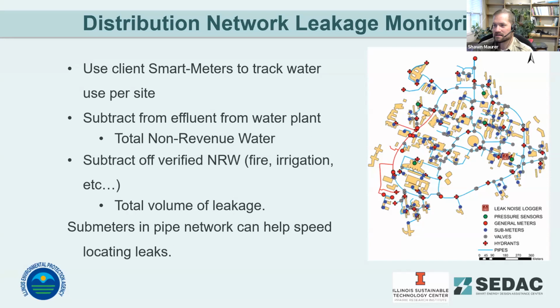And this doesn't have to be an incredibly high cost project either. A lot of water networks are already moving towards smart meters for their clients because that provides the client a notification when they've got a leak in their building so that they're not paying for water they're not using. But now you've got a tracked, metered source of water consumption in the network, that if you add just a couple more sensors to your main distribution lines, you track water flow through that network. If it doesn't add up to what's being consumed, there's a leak there. You can start targeting those areas for remediation.